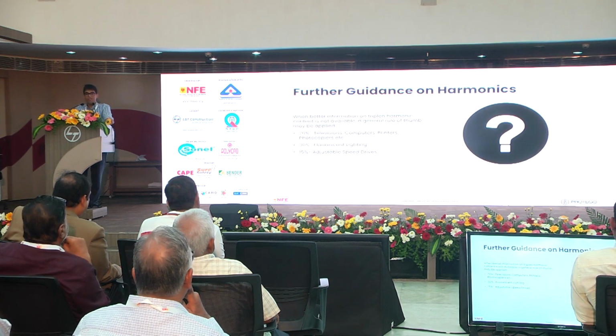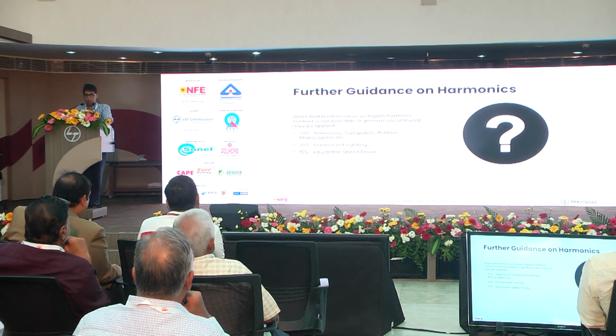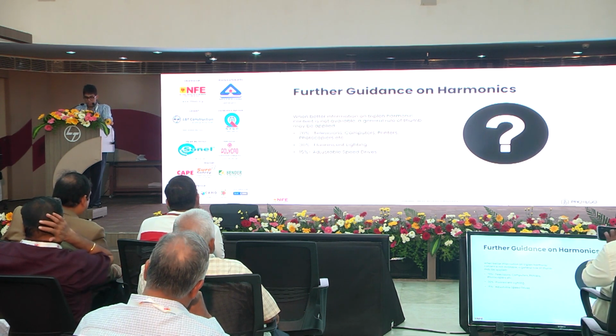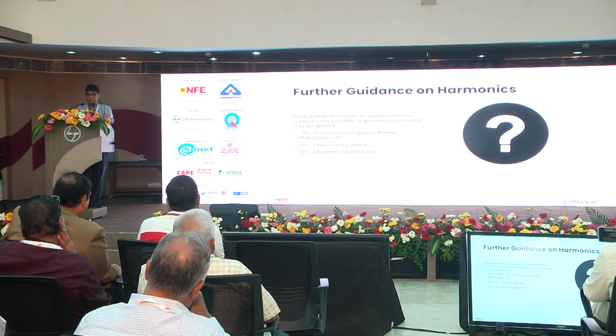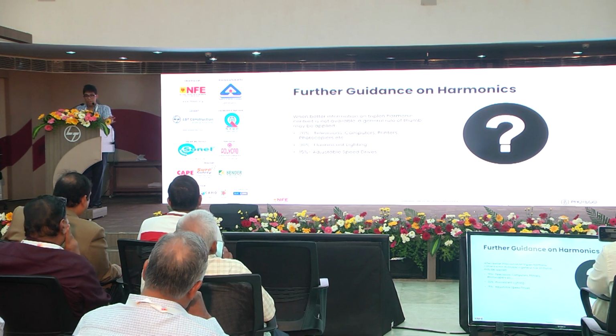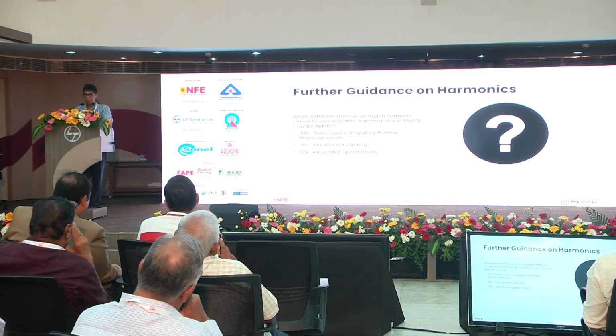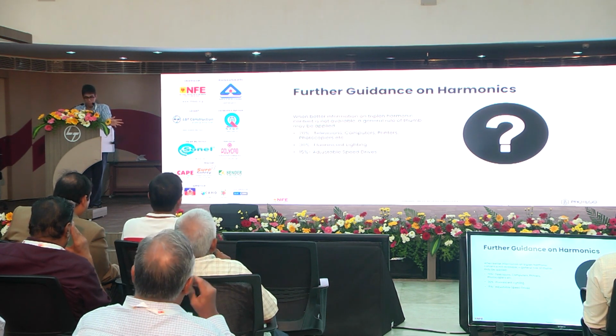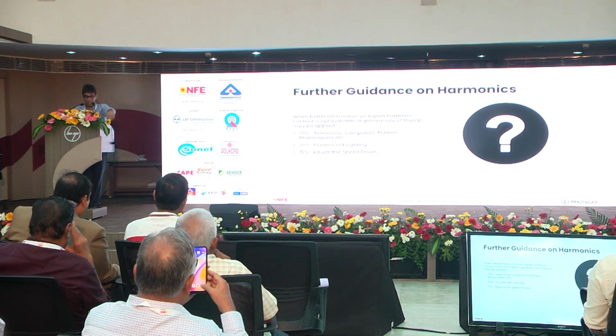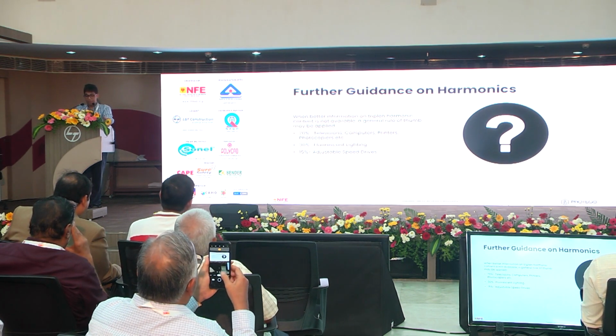If you get no information from a supplier of the equipment on what the triplen harmonics content is, this is what you can assume. And remember, this is a general rule of thumb in absence of any information. 70 percent for televisions, computers and printers. So any circuits with this, you need to obviously do derating. If you have fluorescent lights, 30%. If you have variable speed drives, 15%.